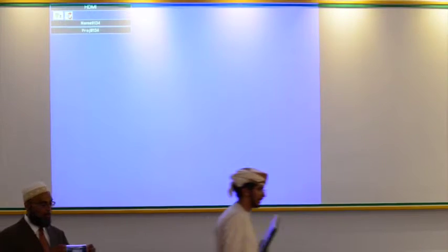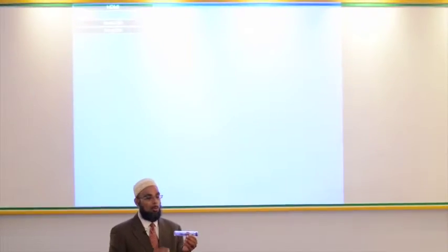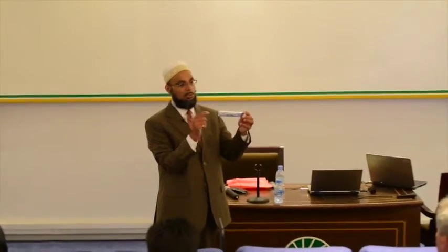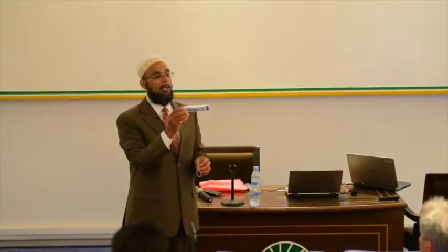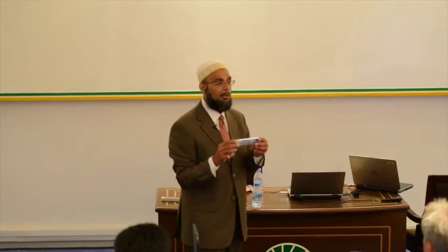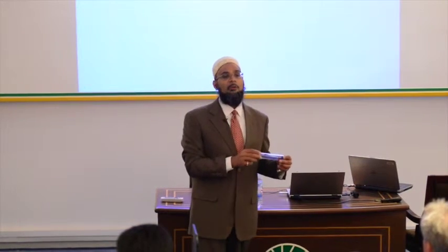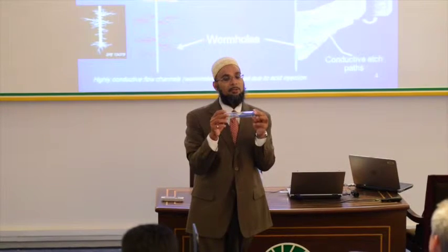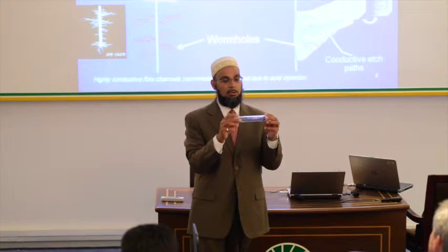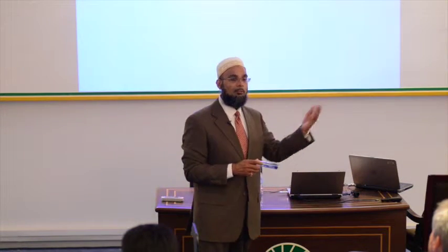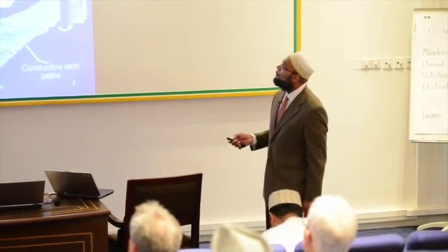This was a core which was about 1 inch by 6 inches, and it was linear flow. We acidized it, right? And then after acid, we did a high resolution X-ray tomograph, and then we printed that tomograph image. So this is the 3D print of the wormhole that was created. It is almost scale 1:1. So these are the wormholes that we would get in the formation also. So this was matrix acidizing.